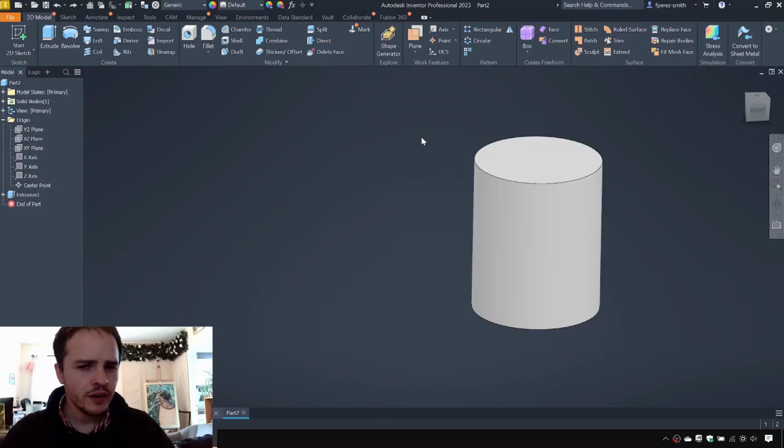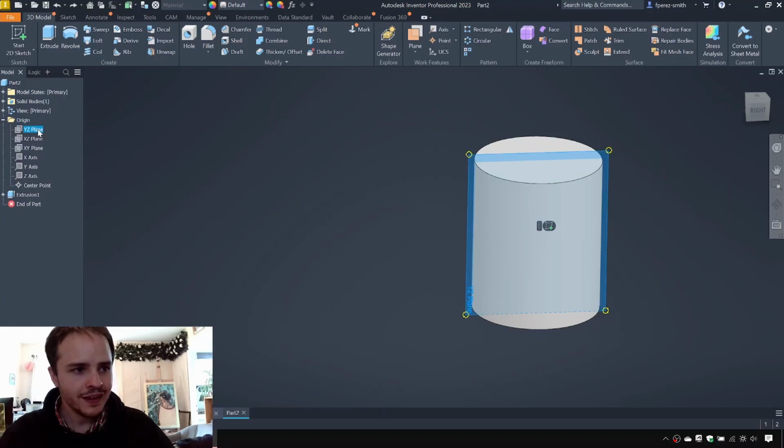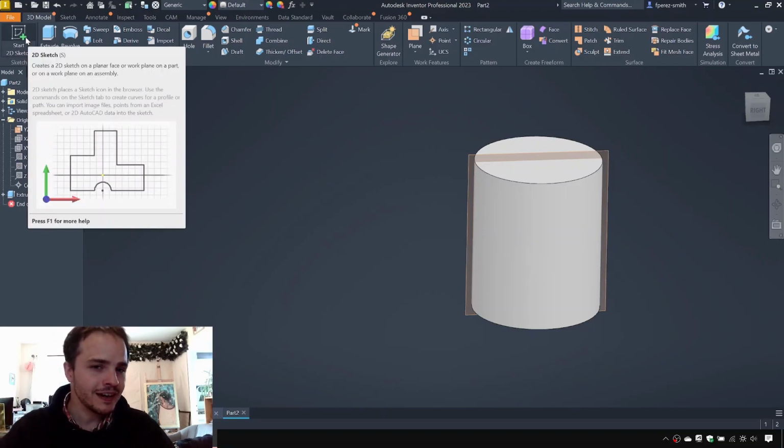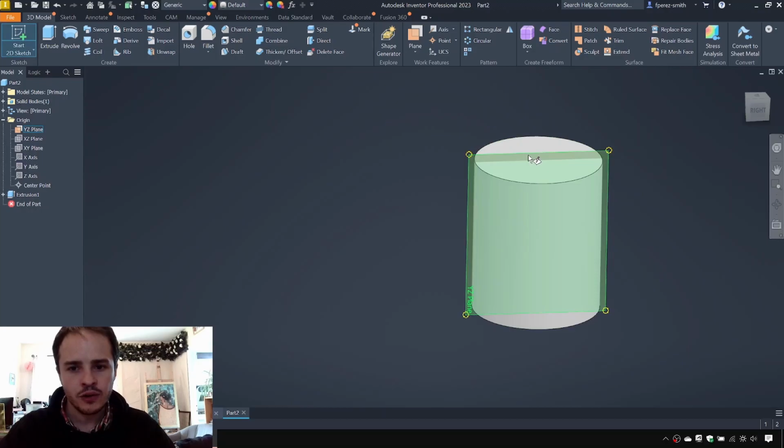Okay, so we are going to capture the 25 up and the 90 across by using a sketch on the vertical plane. So I find it useful first to find the vertical plane and make it visible. So we can find it underneath origin in the model tree. So you can expand it out here. And in this case, for me, it's the YZ plane. So we'll right click it and hit visibility. The shortcut is V. And we're going to specify using a sketch the 90 across and 25 up.